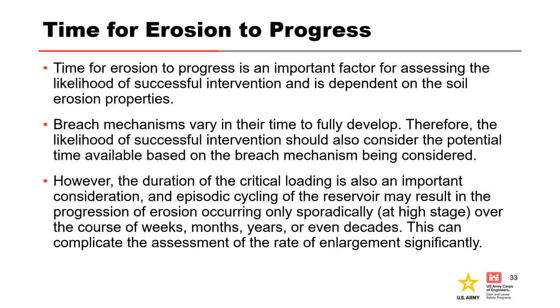The time for erosion to progress is an important factor for assessing the likelihood of successful intervention and is dependent on the soil erosion properties. Breach mechanisms vary in their time to fully develop. Therefore, the likelihood of successful intervention should also consider the potential time available based on the breach mechanism being considered. This is discussed in more detail in the intervention presentation.